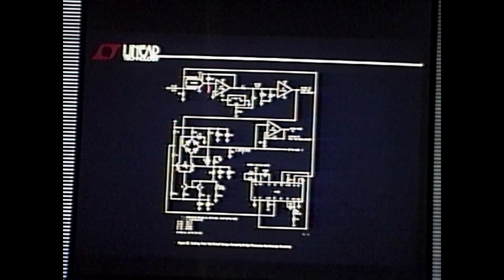The magic of a sampling bridge like this is the approach is fully differential. You remember the sample and hold we had back, I think, in the first lecture, where I used a bridge like this for the same purpose. I was using a 10-pF sample hold capacitor, and I couldn't afford any charge getting through the switch. There's no way I could use a FET. Same approach here. The bridge is fully balanced to the extent that my layout and my timing skew and my drive to the bridge are absolutely matched. There's going to be nothing come out of this thing.